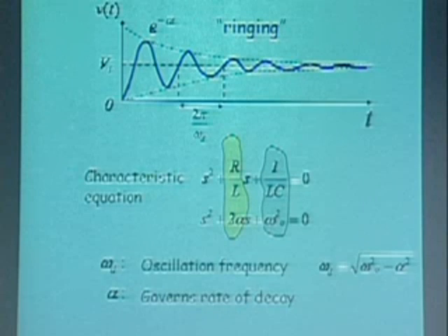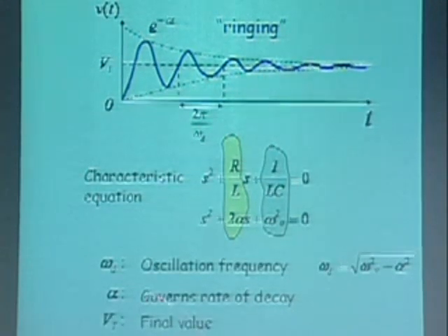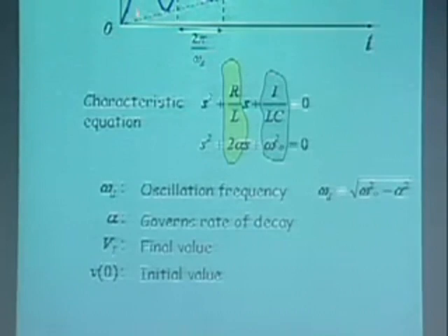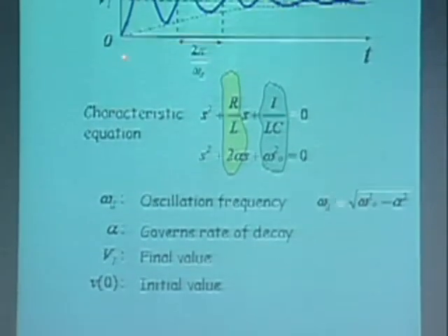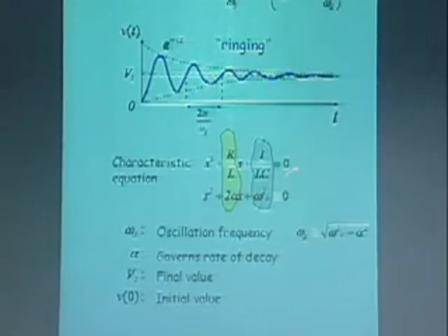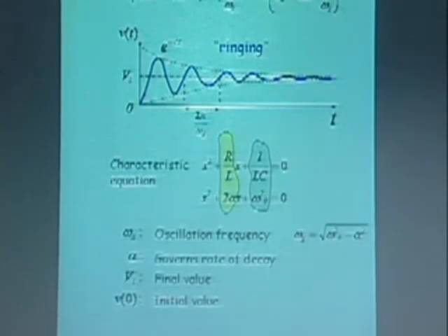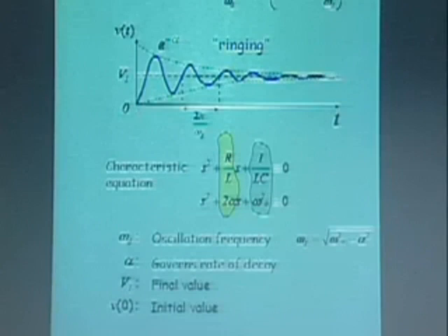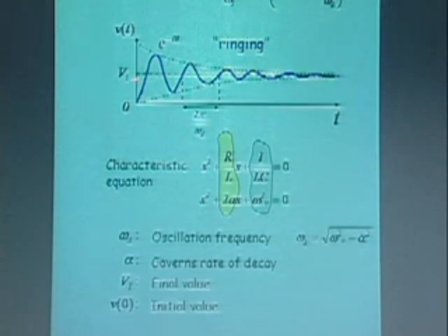It's absolutely unbelievable. Okay? So what are the other factors that are interesting here? Of course, I need to find out the initial values. I start off at 0. This is my capacitor voltage. If I don't have an infinite spike or an impulse, my capacitor voltage tries to stay where it is and starts off at 0. And the final value is given by VI.